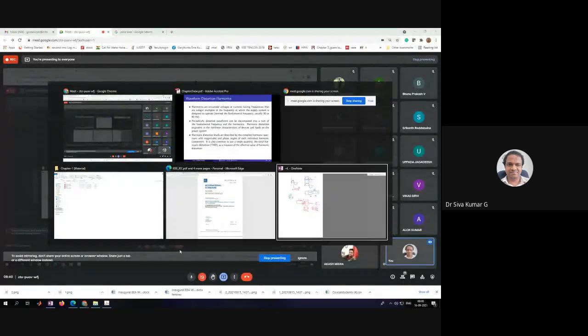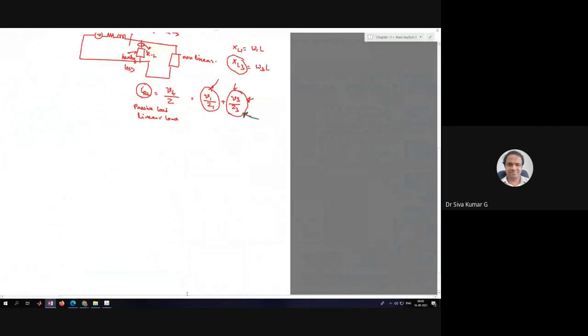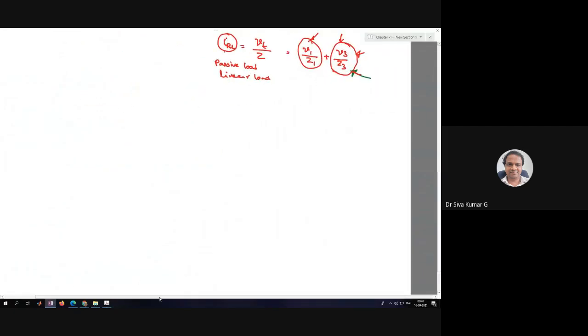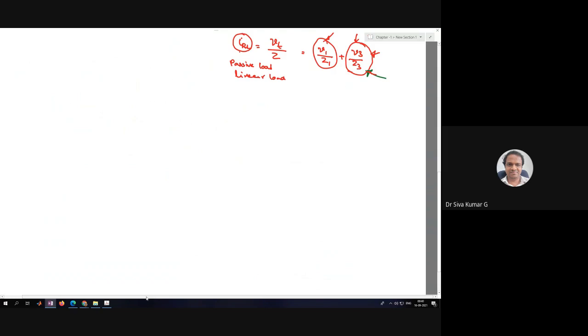In the meantime, I will just give the equation. How do you estimate it? You all know about it also, because in most of our power electronics courses we have been talking about the THD. Generally the THD is equal to the square root of V squared minus V1 squared, divided by V1. Otherwise, it goes as the square root of VDC squared plus V2 squared, if there are any even harmonics, and so on, divided by V1.